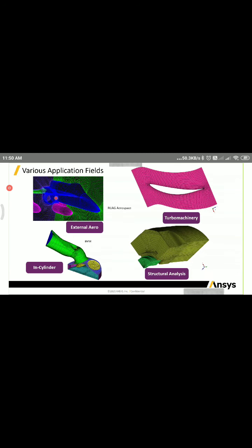Here, if suppose you are dealing with the symmetry, it will be again a C type block. If it is a complete aircraft, it will be an O grid, okay, which is going throughout the fuselage of the aircraft and so on. So there could be different strategies to generate the mesh and to get the proper mesh with the required y-plus. You can go to e raised to power -6, -7, for very fine requirements of high-speed flows of the aerospace industry.